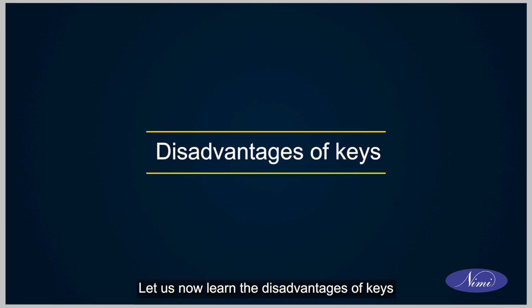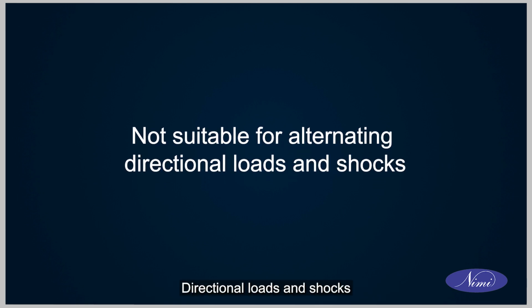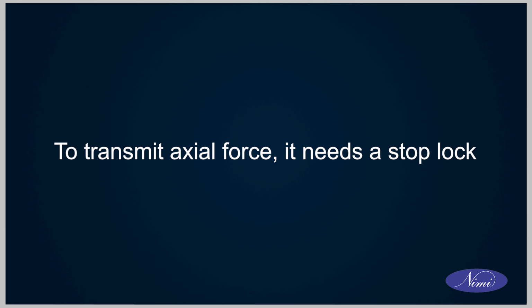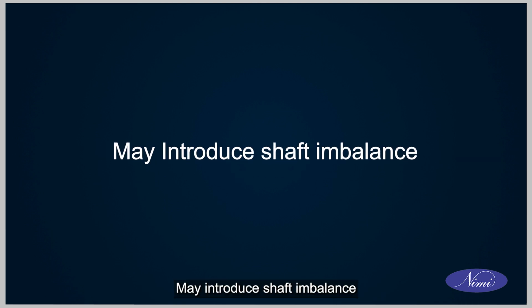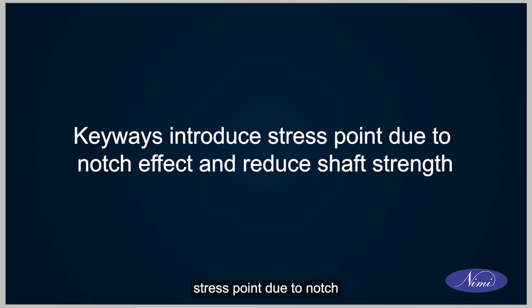Let us now learn the disadvantages of keys. Not suitable for alternating directional loads and shocks. To transmit axial force, it needs a stop lock. May introduce shaft imbalance. Keyways introduce stress points due to notch effect and reduce shaft strength.